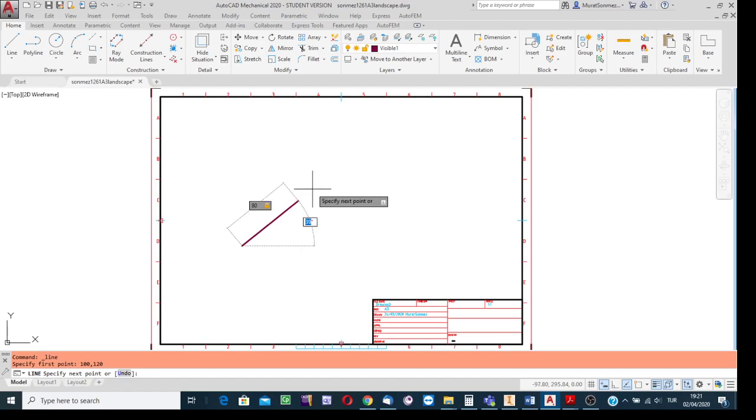If you clicked on the Tab key, then AutoCAD understands that the first number is the length, and you see within the box now we have a lock symbol. It means it has been recorded as the length of the line. And then within the second box now we have a blue background color. This means the box is ready for our typing. The degree symbol implies that it is the inclination angle of the line. See the arc simulation. It is in the counterclockwise direction. Do you know the angle as measured in the same direction?